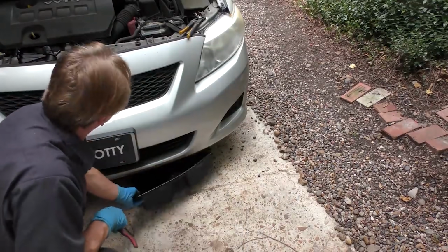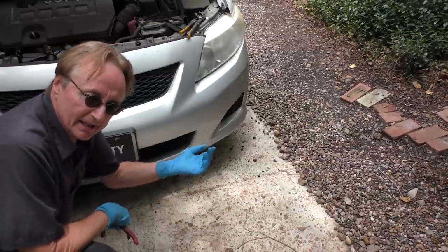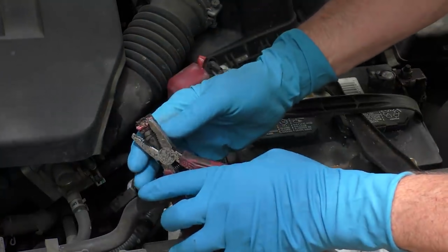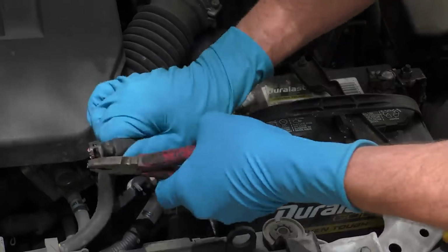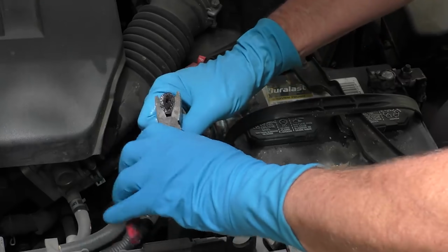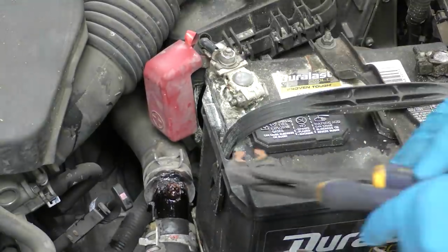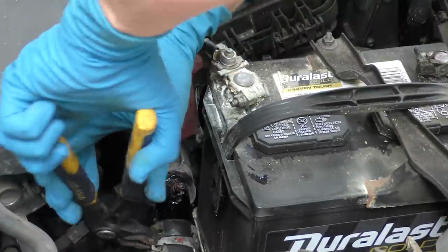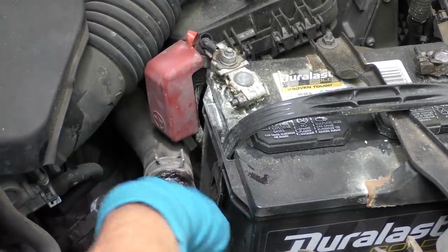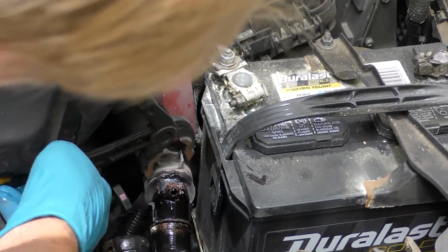First, we'll get a drain pan and stick it on there, so we don't get coolant all over the place. It pollutes, animals can drink it and get sick, so put a little pan under there. Now this broke off, so we gotta take the clamp off. You squeeze it, put it up here. The old piece is kind of stuck in there, so we'll crunch it up a little, and we can pull it out. With bigger pliers, squeeze the rubber hose. And once we squeeze the one side, we can pull off half of it. The rest will go in a drain pan. Then we'll squeeze the other half.